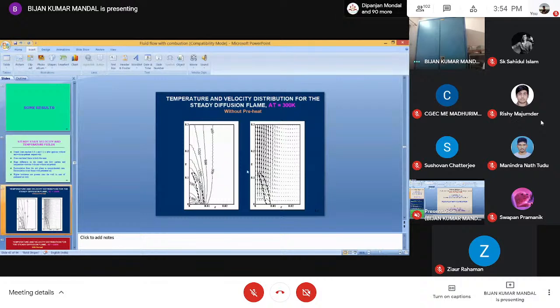Okay, now these are called contours. Contour means this is the temperature contours, that means along this value 400 Kelvin, all these points are at 400 Kelvin, and beyond towards the right it will be less than that. So this is 800, and in between. Normally it is shown in the form of contours. You can see we have started with 300 Kelvin here and 300 Kelvin there. You can see towards the right of this, our temperature is almost 300. So the isotherms are vertical.